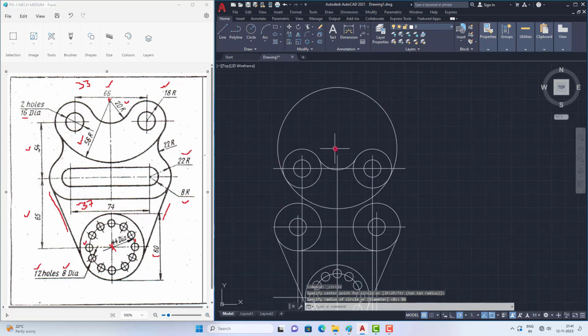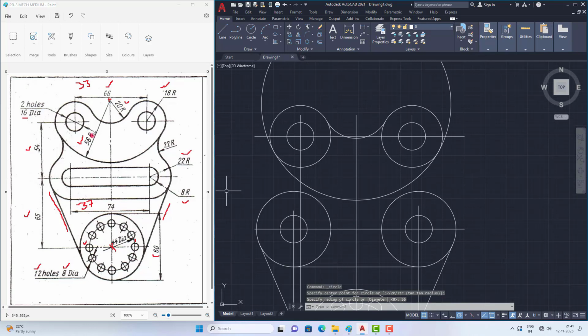Now it will be appearing like this. And now there are fillets here. So there is a fillet here, and here. So we need to give fillet again. So I am selecting fillet and selecting radius and giving the radius value 22 and pressing enter. Selecting multiple, so I am selecting this circle and this circle and again this circle and this circle, so that those will be applied.